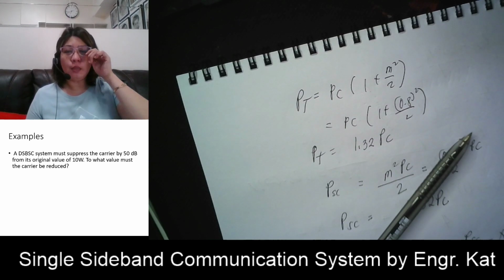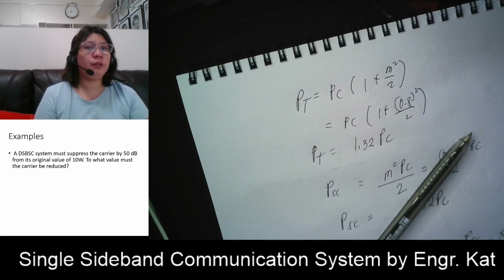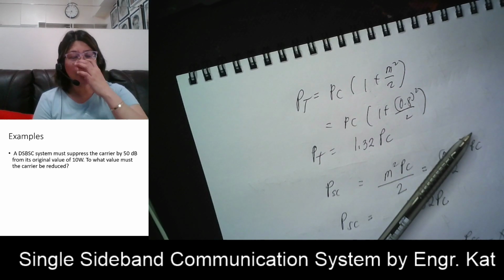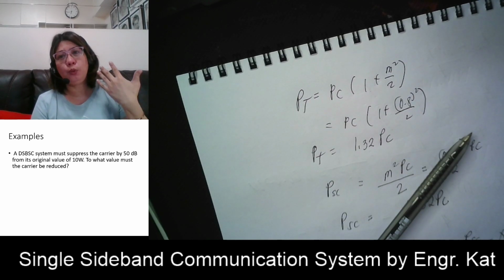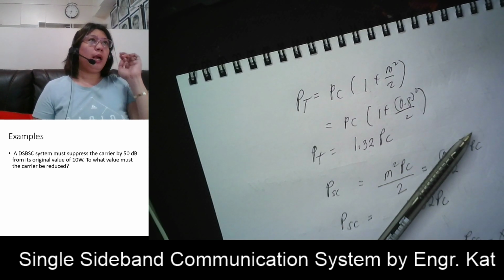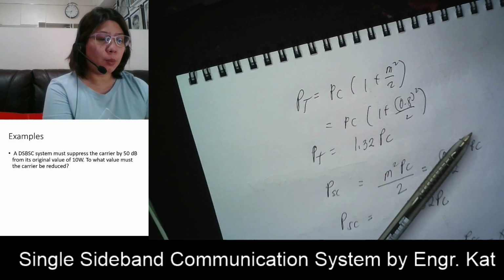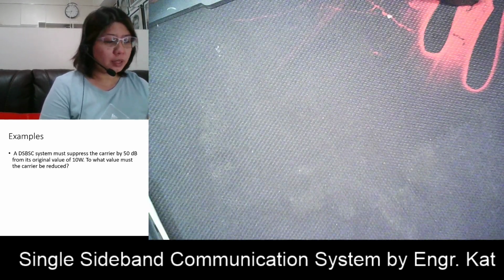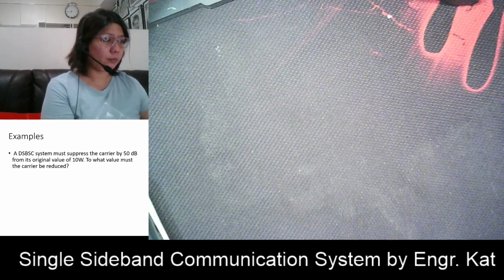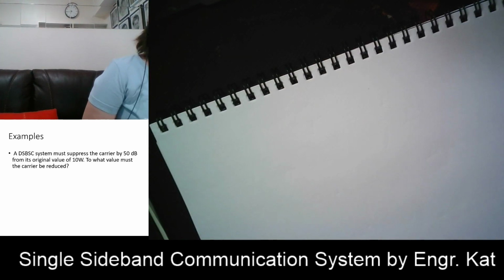So we have here a double sideband system that must suppress the carrier by 50 dB from its original value of 10 watts. Okay, so to what value must the carrier be reduced? Okay, so we need to suppress, or we need to reduce your carrier. So what is our formula for that? Our formula for that is just your simple decibel formula.